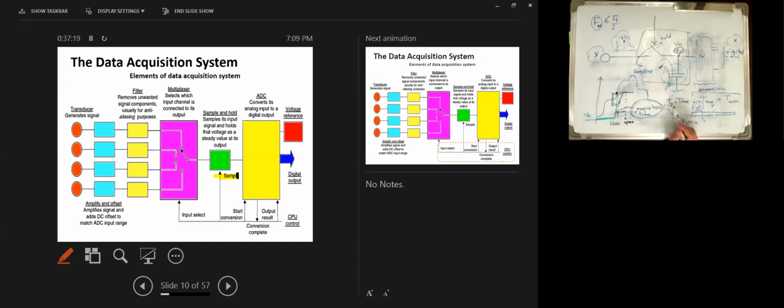So how to determine the sampling frequency of your system? You need to determine the acquisition time and the conversion time, which gives the sampling period, and it is the reciprocal of the sampling frequency. So this is a trade-off. If you want to reduce this error, the acquisition error, which is different than the quantization error: the quantization error is related to the way we quantize the signal.